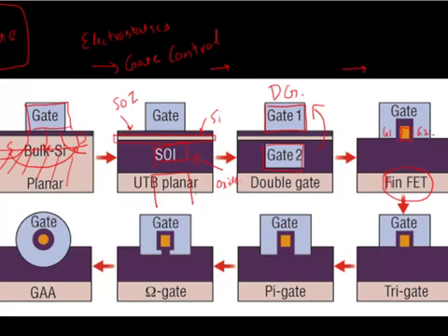The only difference between a fin gate and a tri-gate device is that in a FinFET device you have two effective gates. You have a thick oxide here, so essentially if this is your channel material, this is your fin. In a FinFET device you have one gate here, one gate here, and another material, say a thick oxide or a nitride, on top, so you don't really use the top surface for your transport. So that's your FinFET device.